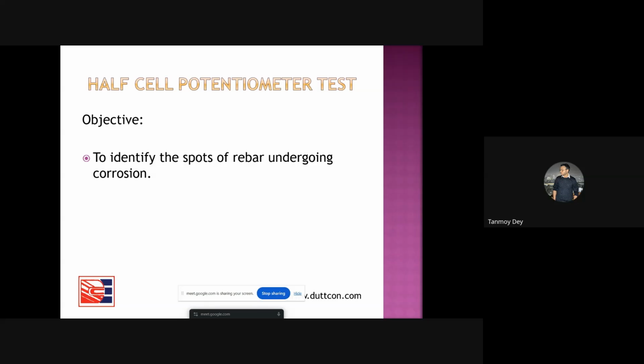So it expands. This expansion has no room, so it pushes against the RCC structure enclosing it. With this push force, the RCC structure gets damaged and cracks are generated.